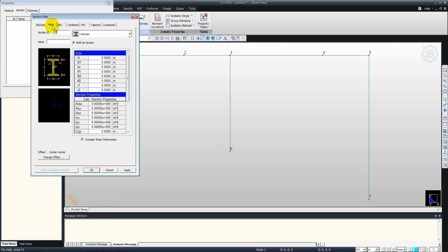So selecting value type section, because in the value type section we can edit or enter our own section stiffness properties. Select solid rectangle, enter the name of the first section as I, and here we type in the IYY, because this moment of inertia represents the rotation about the y-axis, and that is what we are after. We are after the rotation or the moment calculation about the y-axis, the local y-axis of the element which is into the plane. So we select IYY and enter 1, and for the area we enter a larger value, so